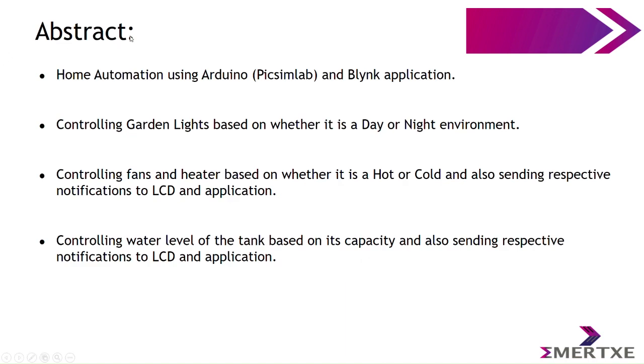What is the abstract of the project? The home automation system uses Arduino, the Blynk application, and Proteus Lab. It controls garden lights based on whether it is a day or night environment. It also controls fans and heaters based on whether it is hot or cold, and sends respective notifications to the LCD and applications. It also controls the water level of the tank based on its capacity.